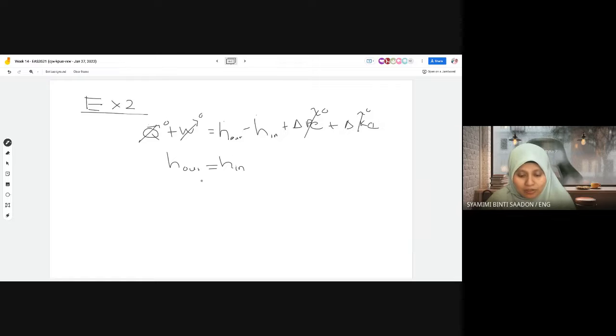Okay, so you can use this assumption. You will get H2 equals H1. Later on, if you look at the table, the same method as exercise 1, you have pressure and temperature, so you look at table A6 and get entropy and enthalpy. So you can assume that enthalpy doesn't change. Enthalpy input and output is the same, 2 and 1 the same. So by using the same value of enthalpy, we search back the entropy S2. So from here you get back S2.